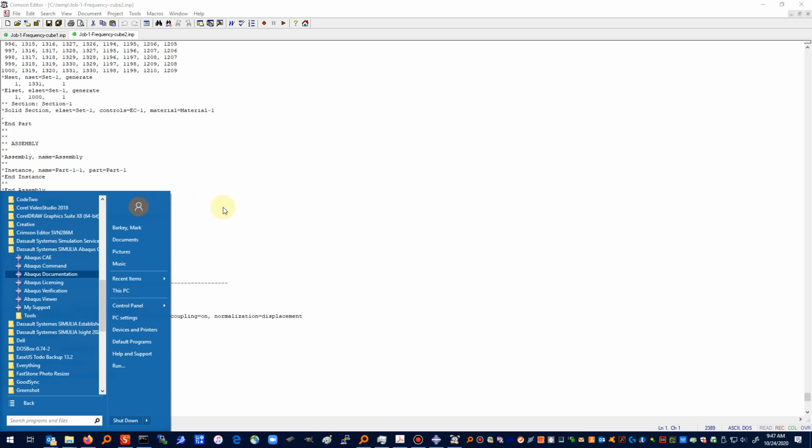Second thing, rotational degree of freedom in shell elements. Default value is 1. Scaling factor for out-of-plane displacement degree of freedom in small strain shell elements, membrane elements, and so forth. Now, we didn't have any other numbers, so if this value is left blank, we'll use the default value of 1. So this is a scaling factor for linear bulk viscosity in ABAQUS/Explicit.